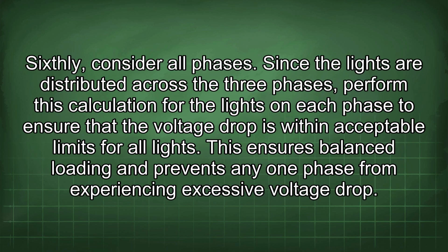Sixthly, consider all phases. Since the lights are distributed across the 3 phases, perform this calculation for the lights on each phase to ensure that the voltage drop is within acceptable limits for all lights. This ensures balanced loading and prevents any one phase from experiencing excessive voltage drop.